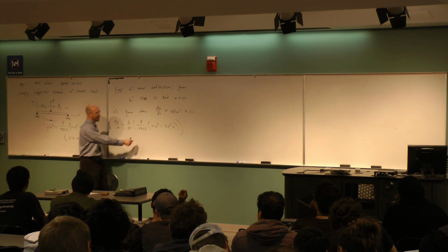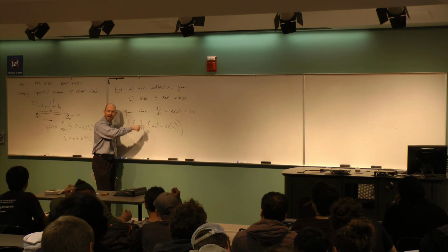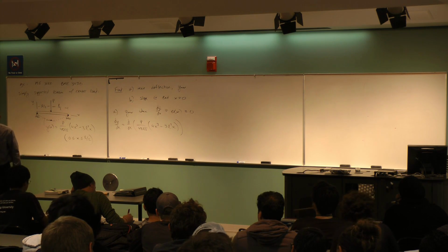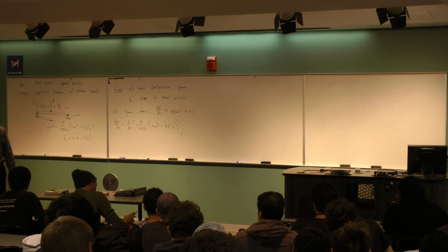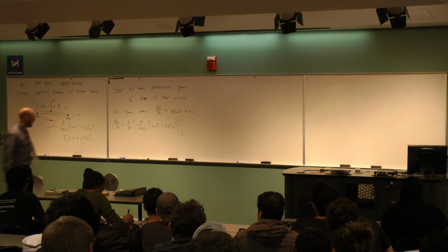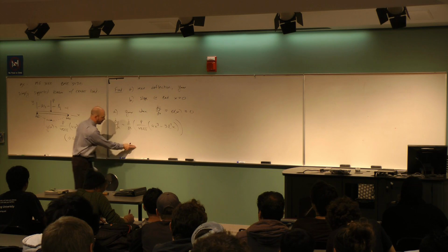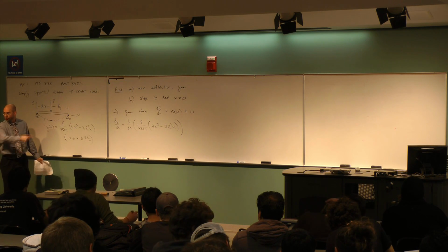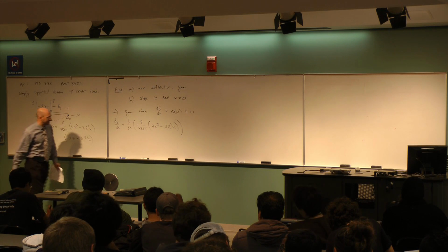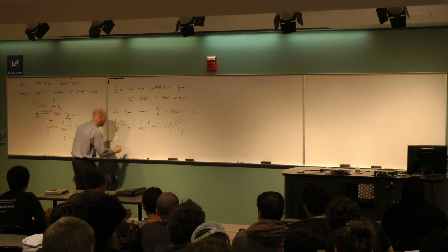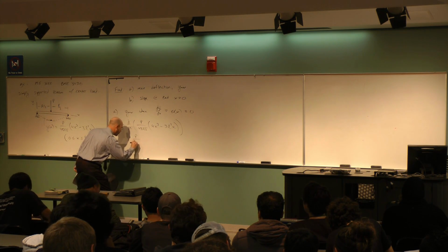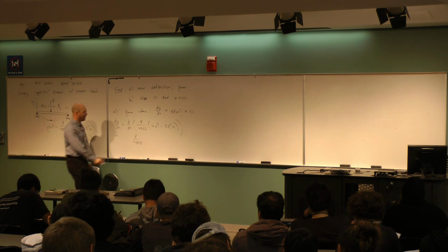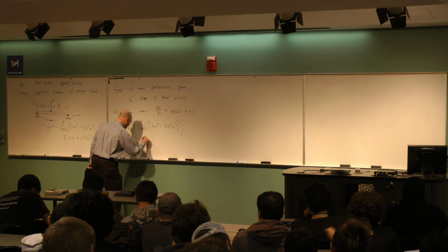If I take E and multiply by I, that entire thing represents really how rigid the beam is. So I can have a combination of material and geometry that makes the beam rigid. That's E multiplied by I, so that's why we call that flexural rigidity. Okay, but the point is, these are just numbers. They don't vary with x. So what I'm going to do is take this out front, P divided by 48EI, and now I need to take the derivative of this polynomial.